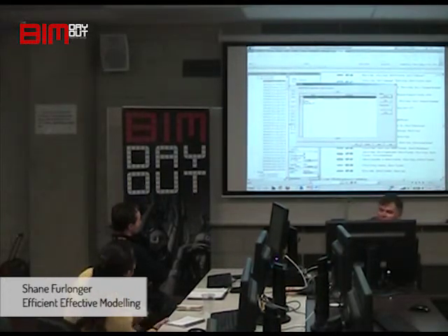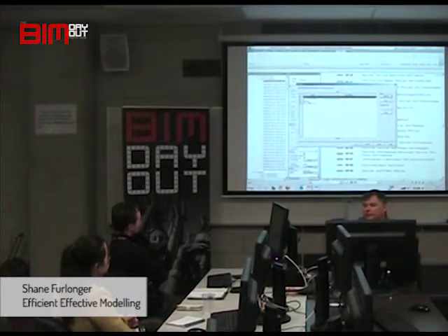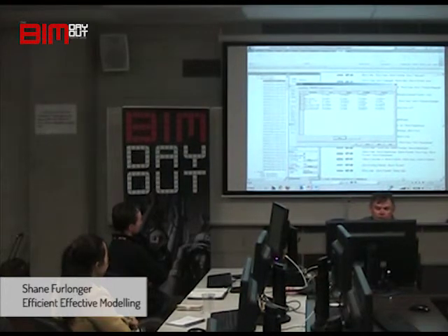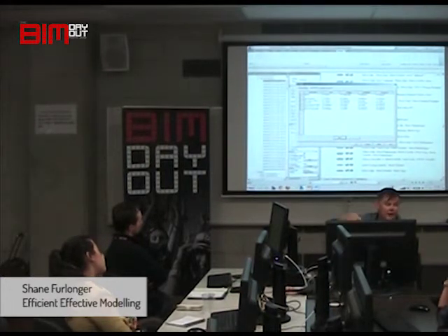This existing is our own wording. We can change that. I could call it anything I like. I could call it Fred. Next one along, this one, this means it's existing in the phase that you've just started. So if I had 10 phases, everything up until the 10th phase that hasn't been deleted or demolished is existing. And it could have been created in any one of the 9 phases beforehand.